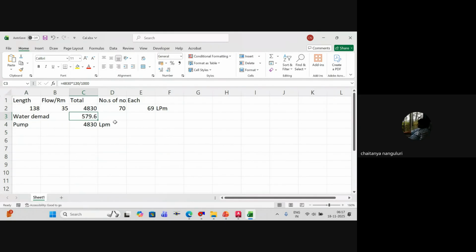That means you already have your sprinkler demand and hydrant demand, right? According to that, you have already calculated a certain volume. So that volume you have already added. Along with that, you will have this one. So when you have, for example, some cubic meters, that and this you have to add together to calculate the total fire pump system.